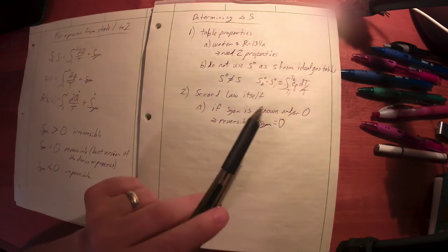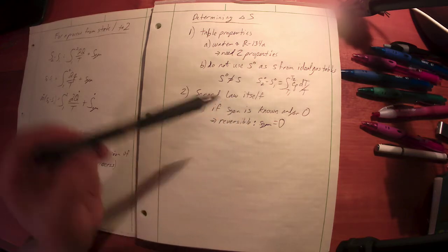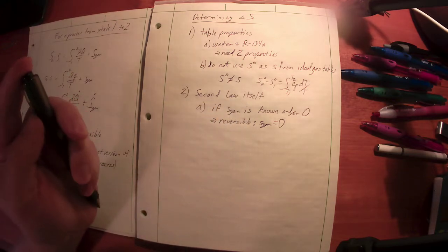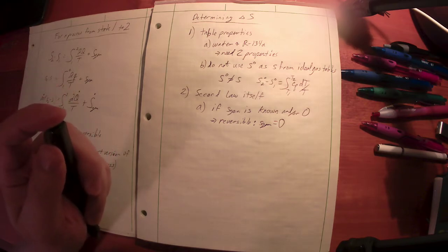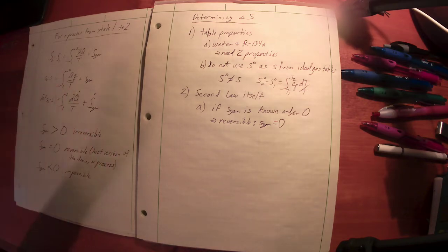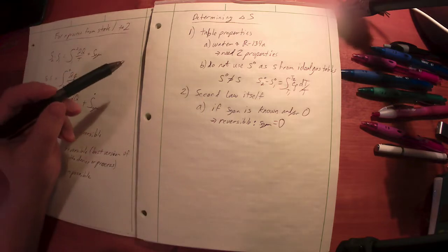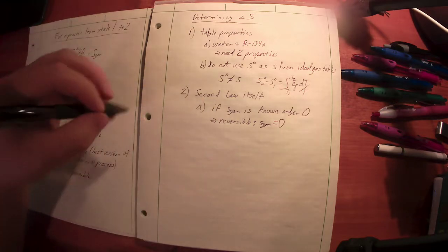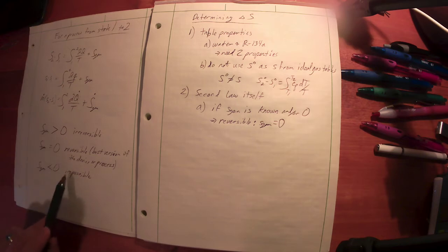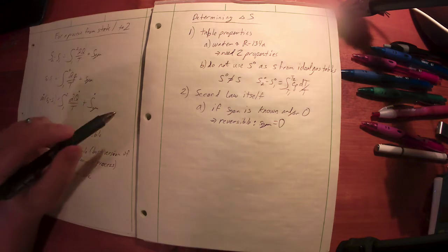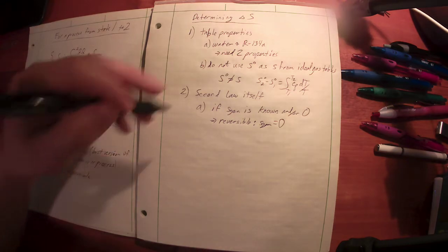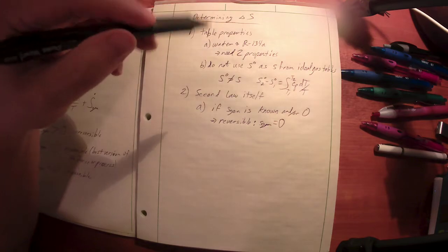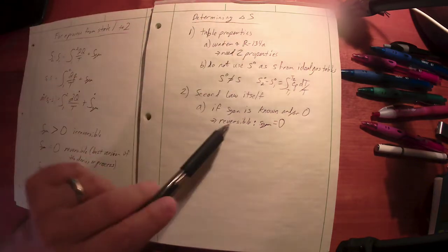It's possible that they might also just give you a quantity for S gen that's a little less realistic, but not impossible. But anyway, it has to be a positive quantity or 0. Those are your options that are possible. If you compute S gen to be negative, that's impossible, and we just say, well, this process cannot exist. It doesn't make sense, or I've missed something, or I've converted my units wrong, which is entirely possible, or done some algebra wrong. Anyway, we could use the second law itself to determine delta S.